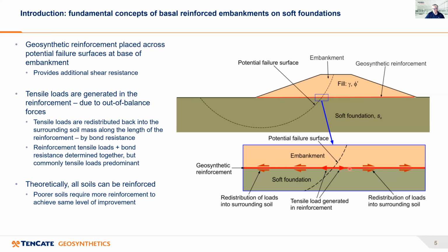So that when we come to calculate and analyze this problem, we calculate the reinforcement loads, but also we calculate the bond resistance as well. Normally, we don't think about the bond resistance so much because it's common for the tensile loads here to actually predominate. So most people talk a lot more about this.